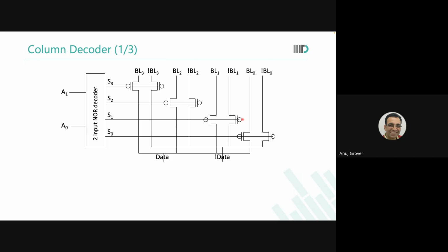Very less area. Density. Just one transistor. If you try to build the other MUX with AND and NAND gates, there will be so many transistors you need to handle. Additionally, for those MUXes, you need a full VDD by 2 transition, everything. You need a full transition. Can you afford that? No.